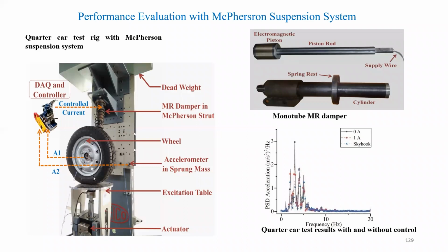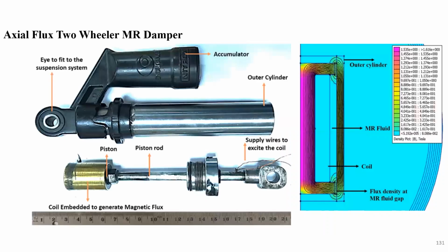The same thing: they have an excitation table to excite this, and after that excitation, you see how this is going to dampen that vibration. They have studied that for various frequencies. This is an exciter. You excite it at different frequencies, and for each frequency, how much current is required to absorb that vibration can be studied here. That's what suspension system studies are. And then you can capture these readings using the NI DAC. So these are all real-time studies.